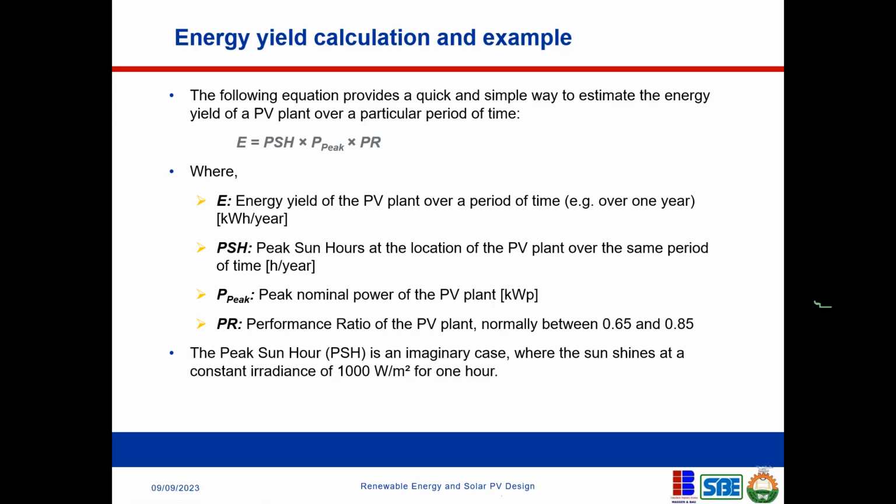when the sun comes out in the morning, so let me use Nigeria as an example. I was working with a client, and I said, sir, the peak sun hour that I have considered for this project is 4. The man said, no, why would you say 4? The sun comes out in the morning, by 9 a.m. the sun is out and the sun is there till 5 p.m. And if you calculate that, that is about 9 or 10 hours. Why would I use 4? So I have to now begin to explain. This same explanation is what I'm trying to offer here.